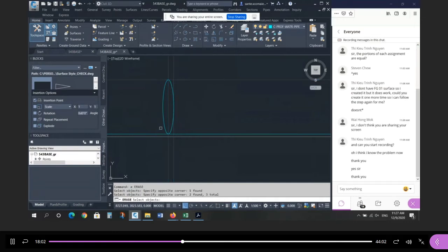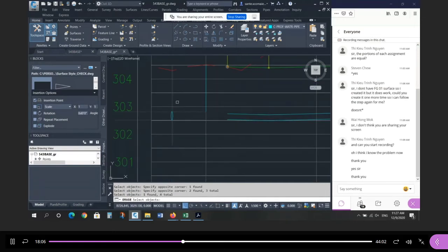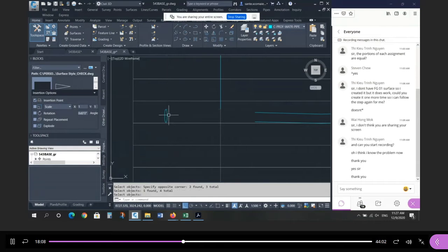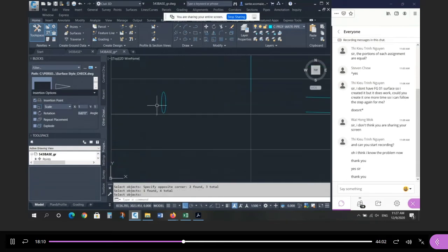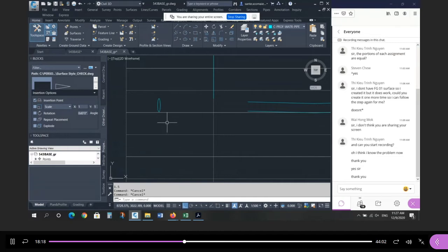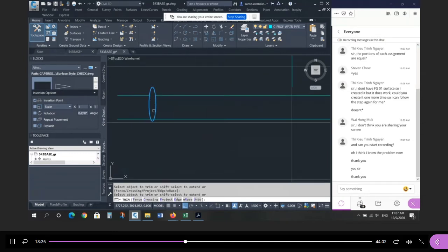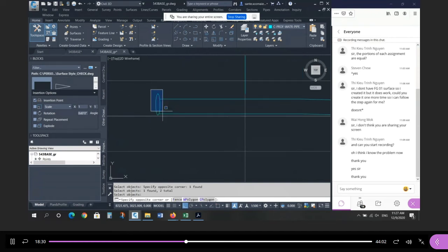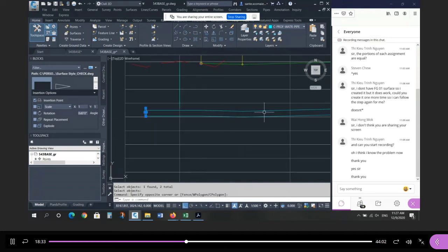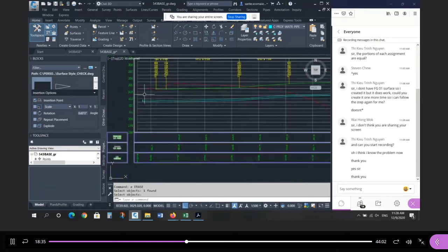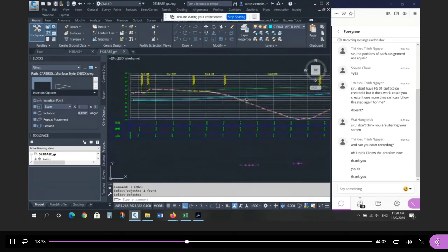So that's the existing water main, at the correct depth, at the correct position, with the correct size. Did I do that right? Calculate 0.3 times 5. 1.5, yeah. And then we can just take the water main across to connect to it. Yep. Trim it here. And this could be existing, and there's your proposed, and there's your entire water main through it. That's how you draw the water main in profile.